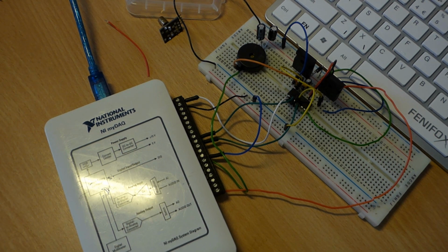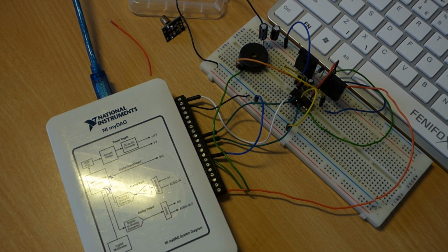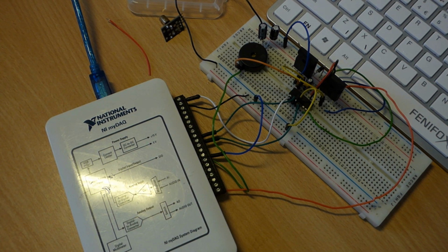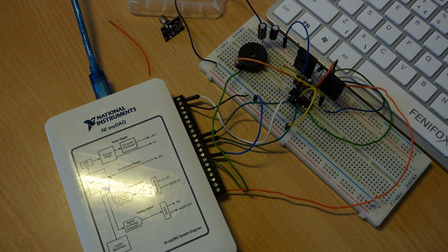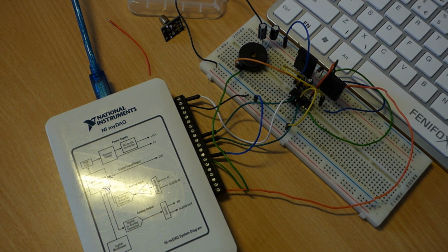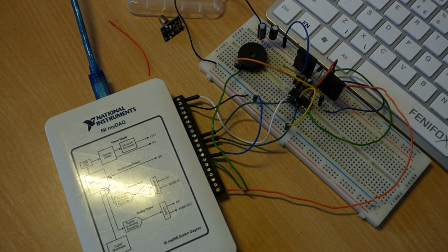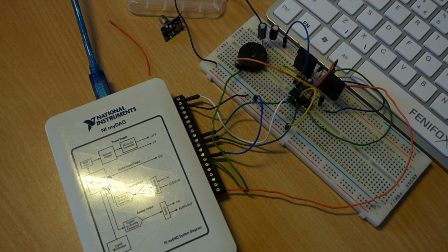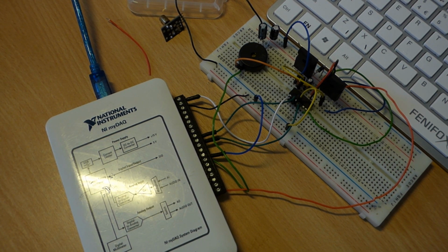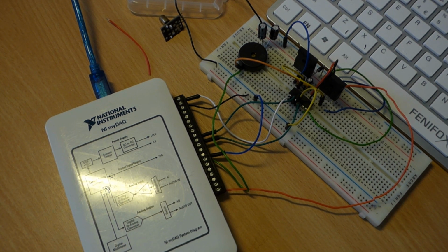You'll notice that if anything happens on the PC, then it will stop refreshing, or the scheduler will stop working with the myDAQ quite so much, and that means that you do get lag. So if I do something that causes this to become laggy, there you go. You can almost hear how often it's being attended to by the scheduler, because it's got that repetitive lag to it.